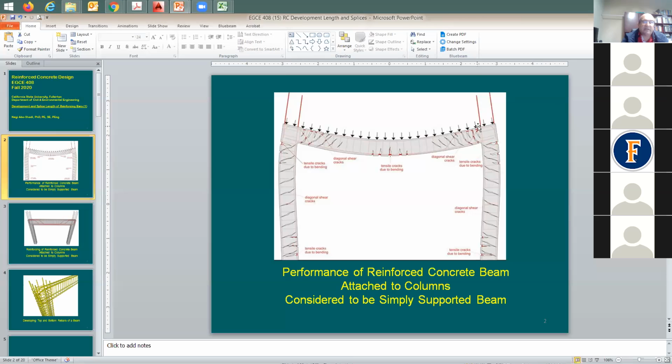You have here the bars at maximum tension. Can I just stop the bar here? Just imagine that you have this rebar embedded in the concrete. Now you start to pull it, right? Now it's going to come out. So you really need to hook this rebar at the end. How would you do this? You bend the top rebar down, and with that you provide a hook. This hooking the rebar or anchoring it to the concrete, we call this development. And this development, you can have it by providing an anchor, or you can have just a much longer piece of the beam that sticks out and just extend the rebar.